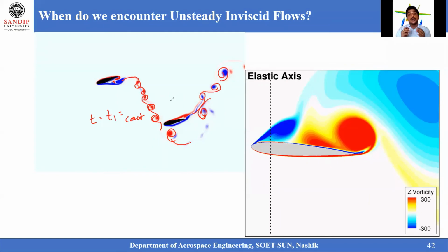Now the question comes, sir, how do we practically approach this problem? Do we need to know how much time it takes initially for the plunging motion or complete wave motion on this particular body? In order to address this practically, using any CFD tools, what we generally do is initially solve the problem as a steady fluid flow. Be very careful about this one. Initially we'll address this problem as a steady fluid flow.